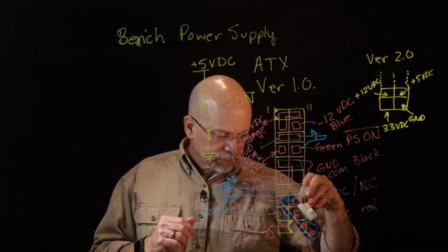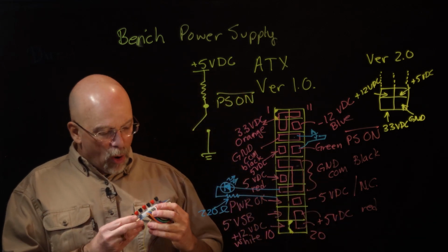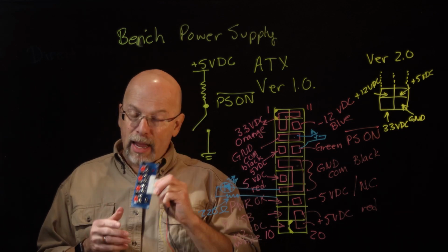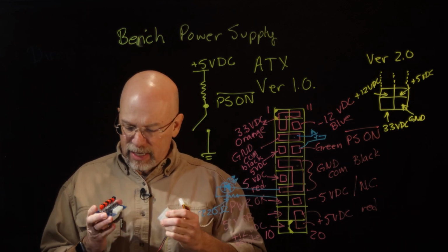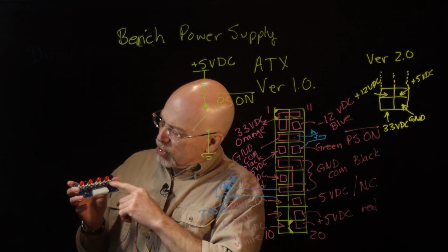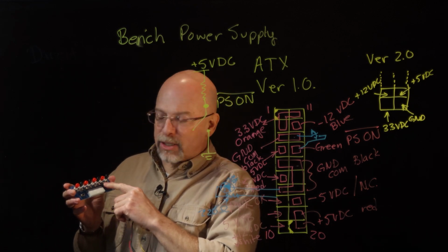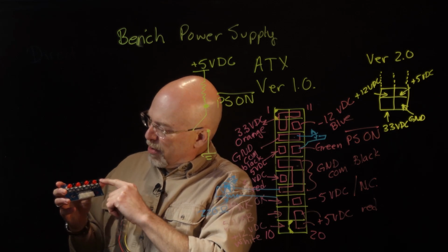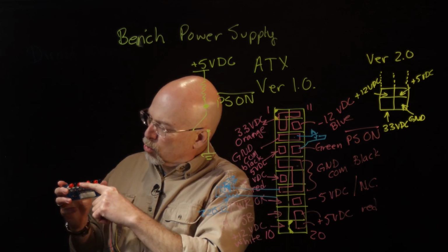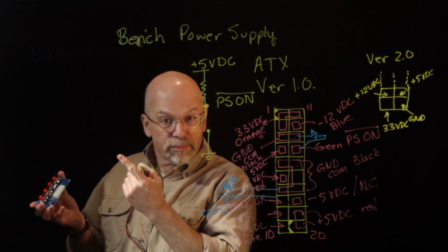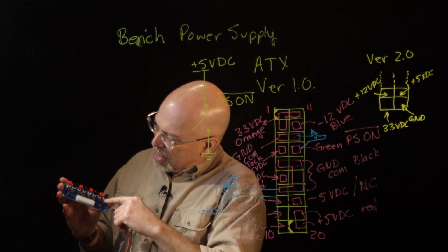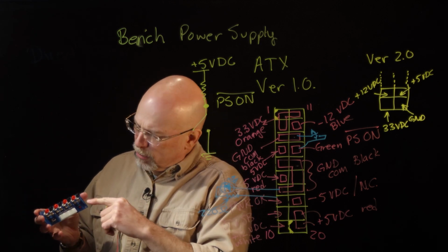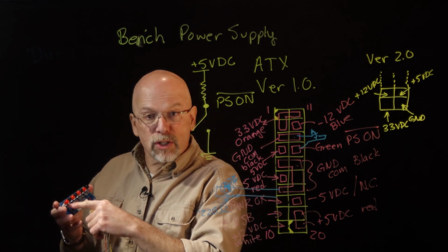For example, you could, on the web, just purchase one of these little breakout boards. Now, this little breakout board has actually got a couple of things that I'm happy about. For example, it has fuses here so that if any of the voltages, so we have access to 3 volts, 5 volts, 12 volts, and minus 12 volts, pretty much what I was saying before, right? If any one of these gets connected so that there's too much current flowing, one of these fuses will blow.